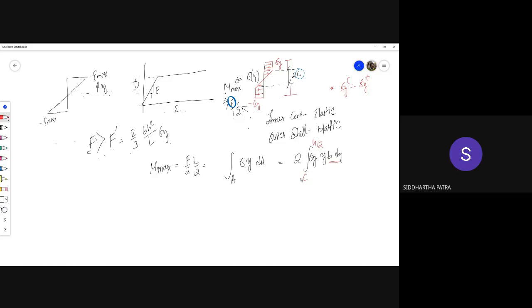So bending moment, you can imagine what happens to the other side. The stress is negative. Also, the y coordinate is negative. Together, they will be making a positive quantity. So this integration just happens twice. And then the other term, where I need to put 2 once again, because the integration is from minus c to c. So twice 0 to c, but this time the stress is sigma y times y by c. You see the stress is changing proportional to y.